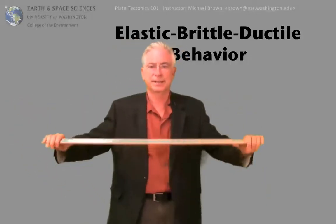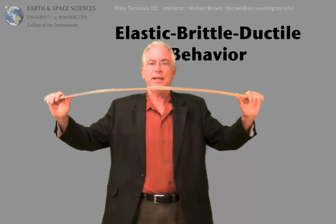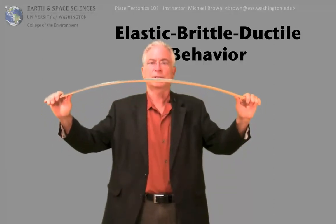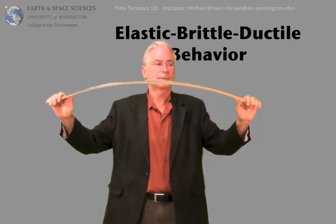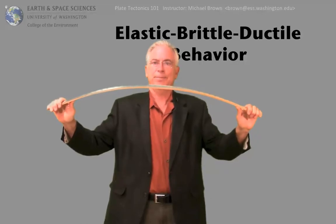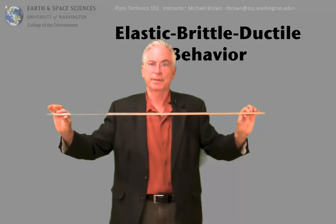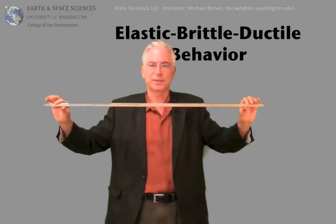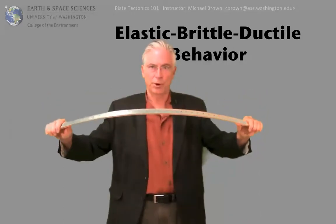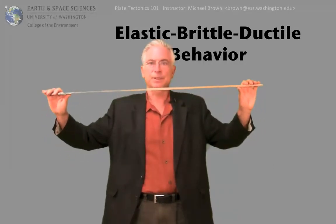I brought along my trusty yardstick to demonstrate elastic and brittle behavior. Elastic behavior involves applying a force, there I've applied a force, and causing a material to deform. See, it's arced here. This is a strong ruler. Okay, it's deformed, but when I remove the force, it returns to its initial shape. So an elastic response of a material is to deform under the presence of stresses, but return to an undeformed state in the absence of stresses.